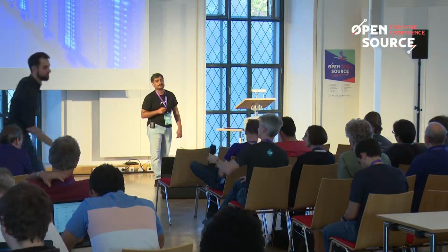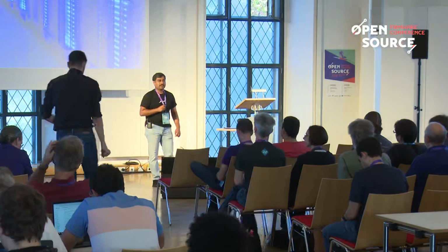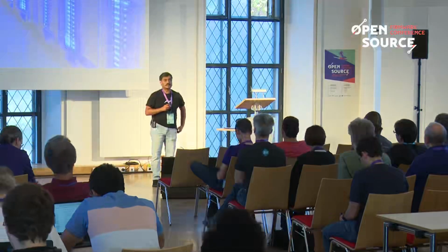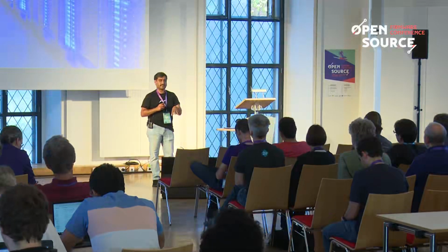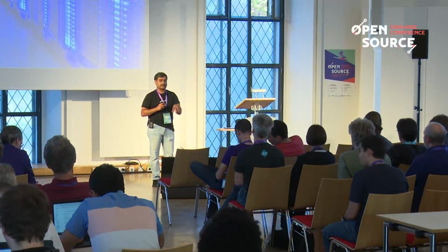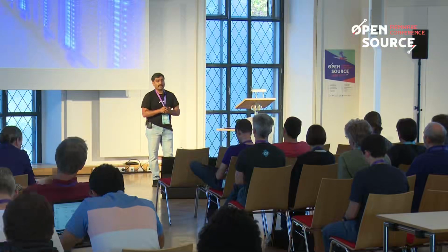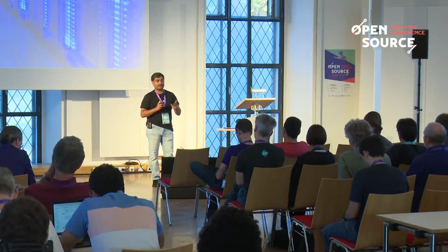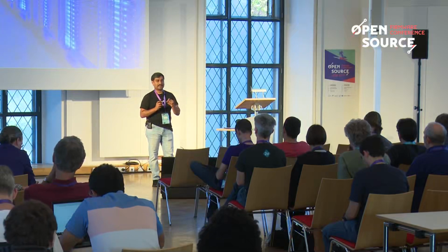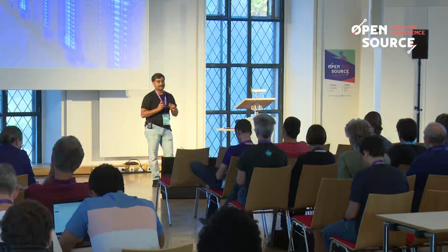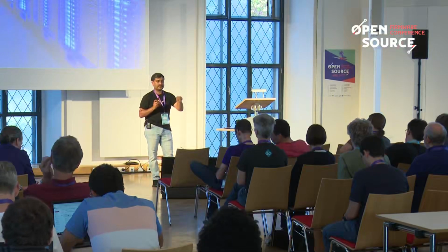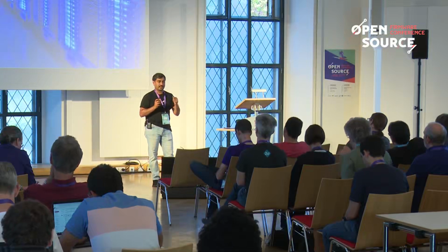That's a great question. We spent a lot of time, almost 2 years, on making sure OpenBMC itself has verified boot, because it needs a lot of hardware changes. Within Facebook OCP hardware, we added a circuit to have the TPM and dual SPI flash with read-only, to enable verified boot on the OpenBMC itself. But we are not authenticating the BIOS firmware; it's only within the BMC itself when it boots up.